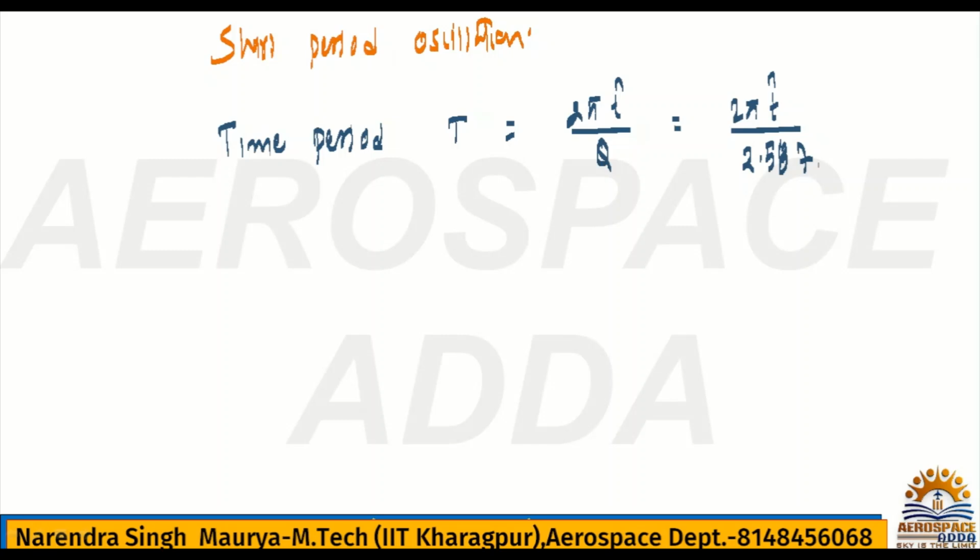First we will finish the time period for the short period oscillation only. So time to half, for the short period oscillations, was denoted t1 by 2. If you calculate t1 by 2 for the short period oscillation, as explained, it will be 0.693 divided by the real part. This formula I had given in the last lecture.